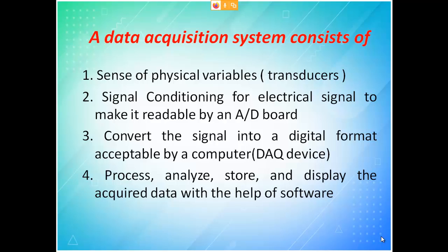Only after removal of the noise should you go for analog to digital conversion. Otherwise you will not convert your input, rather you will convert your noise.